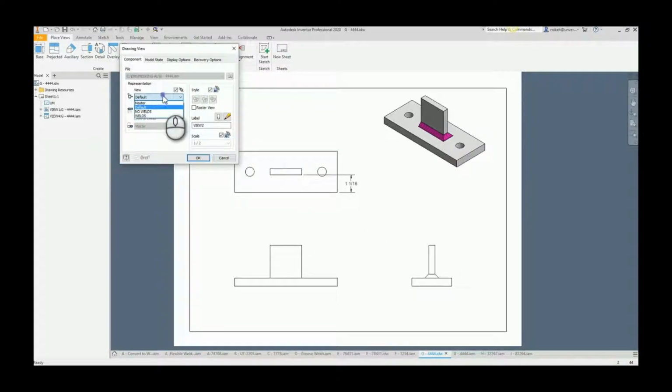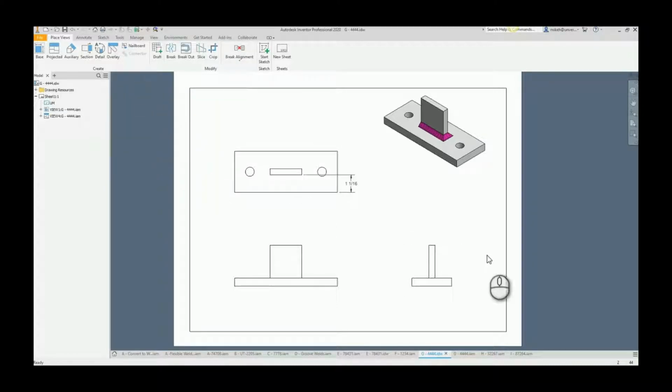And you can have these styled off of the parent as well. And you can actually pick that when you generate the welds too, so you don't have to come back and do this. So now we have clear, clean views to dimension to and show dimensions to, and we know what to pick. We won't have the chance of accidentally picking a weld.